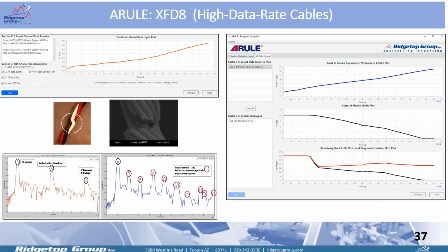So we devised a method very similar to time domain reflectometry. This was frequency domain reflectometry. And we're able to detect damage of broken strands, as indicated by the difference between the bottom set of plots on the left-hand side, which is undamaged. What you see there are the three peaks when the data is transmitted, when it's reflected, and when it's received. And you can see the difference between that reflection plot and the reflection plot of a damaged cable.